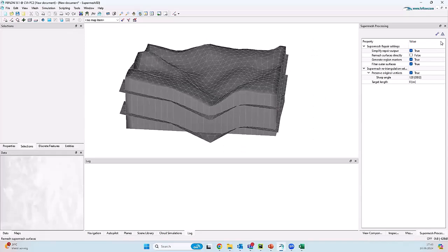In the case of remesh, which basically means we retriangulate the surfaces, we do this process surface per surface, and we do not consider any potential connectivity in the surface. It's something that you need to be aware of. So the vertices of the surfaces could be moved and could also create self-intersections unintentionally. So you need to be careful with this.